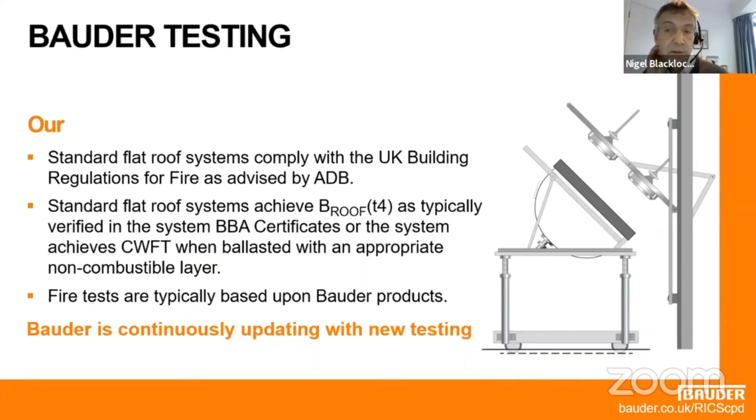Now, one important point is if you come across a test certificate, we will typically test on an OSB or plywood deck. The reason for that is because it's deemed the worst case scenario. So there's no point in testing on a steel deck or a concrete deck, because then you would still have to test on a timber deck, because the timber deck is classed as worst case. That is just to explain why you might commonly come across that a fire test is on a timber deck.